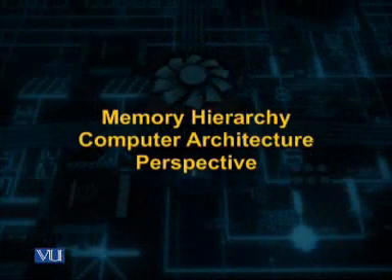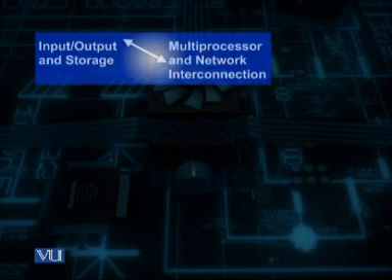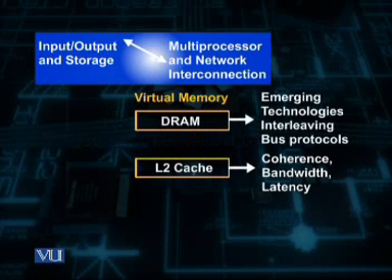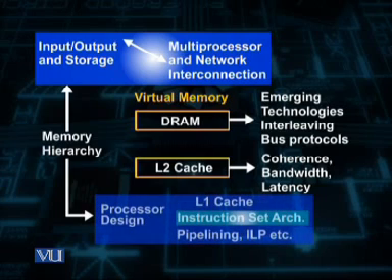Having talked about the processor design, then the memory hierarchy. Memory hierarchy, in fact, deals with the organization of memory at different levels of the design. For example, the level 1 cache memory is usually placed inside the microprocessor chip, whereas level 2 cache memories are kept outside the microprocessor.